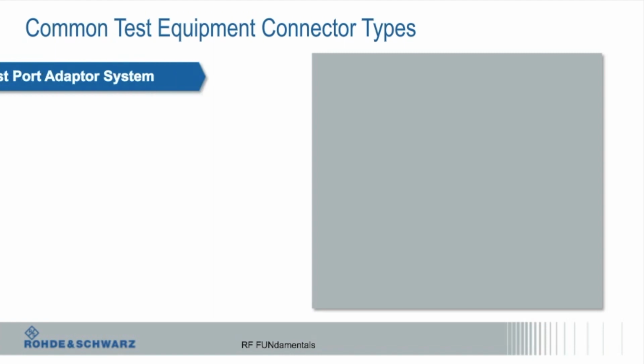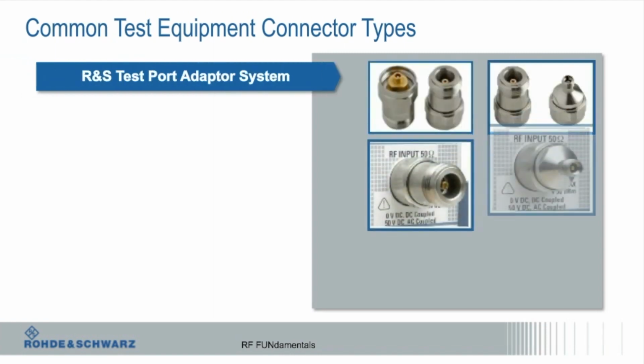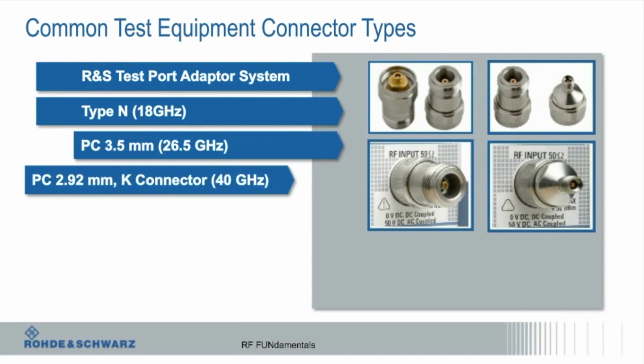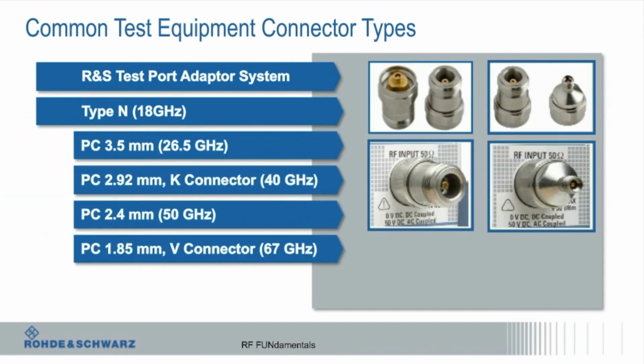One thing to mention on our instruments, not a VNA, we have this adapter system. That little thing there is not an end connector. When some guy has one of these on the front panel of their instrument and tries to bolt something on with a pipe wrench and messes up the connector, I can come in and be the hero, take that off and put a new one in, and you can go on your merry way. Maybe charge you a couple thousand dollars. So that's kind of like a connector saver, but we only do that for N-type.